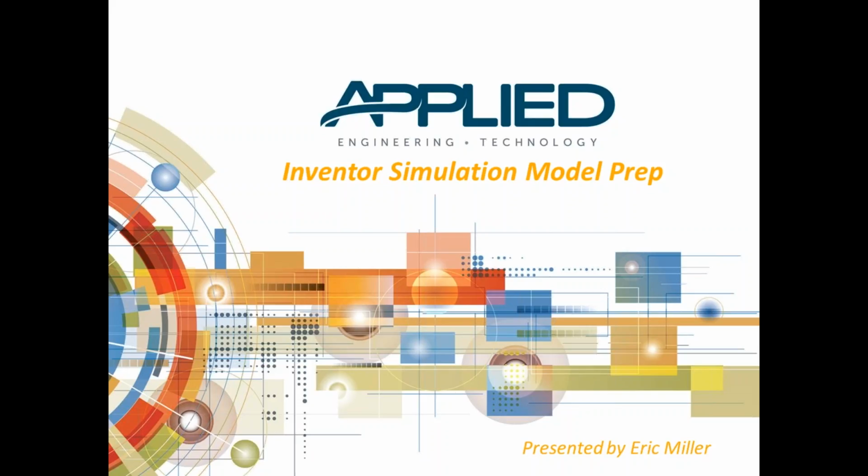But once you get into the actual task within Inventor, one of the key things up front is to simplify your model, prepare it for the simulation. Before you even create a mesh, we want to try to figure out the types of elements that we want to use, and then get rid of the stuff within your model that maybe you don't need. So we'll talk about that a little bit today.